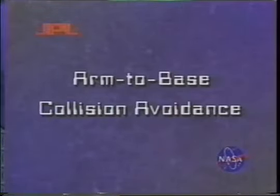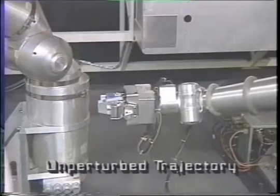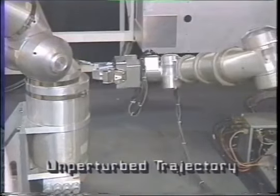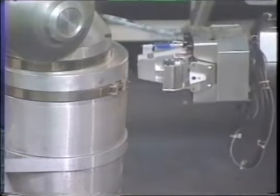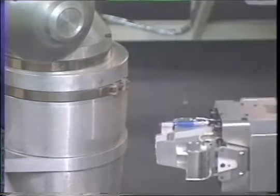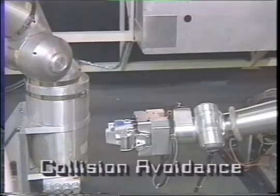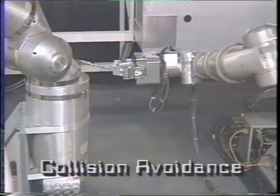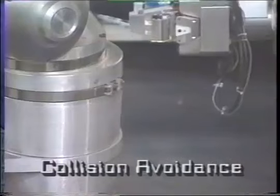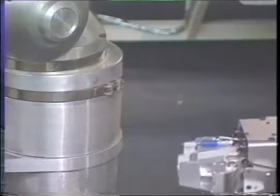This experiment illustrates position perturbation for avoidance of a near collision between the right arm and the base pedestal of the left arm. The right arm is commanded to execute a trajectory which, with collision avoidance turned off, takes it within a centimeter of the base of the left arm. When collision avoidance is turned on and the arm is commanded to move along the same trajectory as before, the end effector position is smoothly perturbed to automatically maintain a user-specified distance from the left arm base.